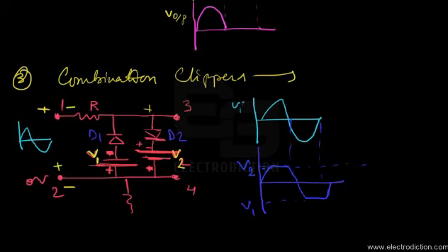So here we can see, if we compare the waveforms, that due to connecting certain voltage sources to the diodes, as the input signal was beginning to produce an output signal having the same shape as its waveform, the DC voltage levels present on the cells have clipped off the output of the circuit, preventing it from reaching the peak voltages of the input signal.